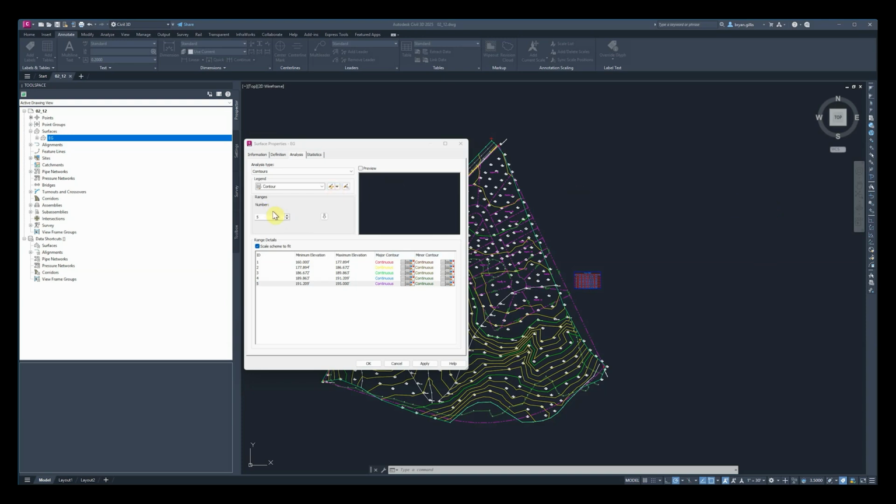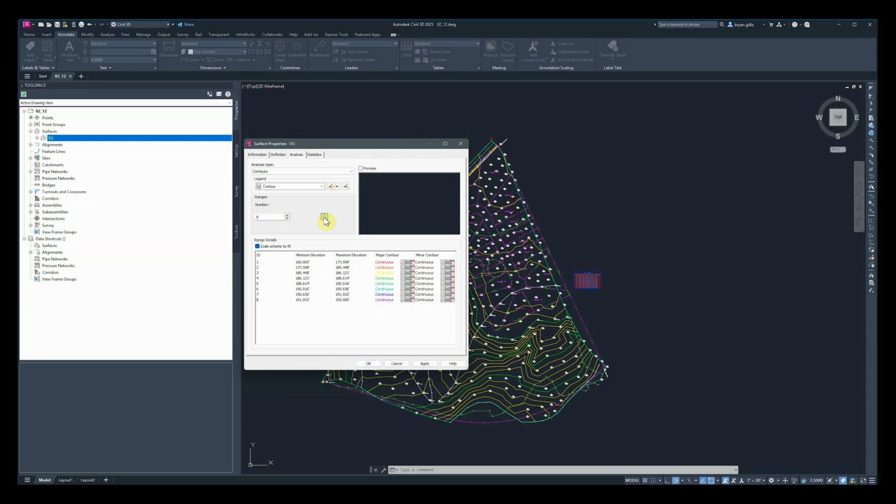So imagine we have these 5 here, but maybe we want to increase our equal interval classifications to 8. So go ahead and change that number to 8, click that Run Analysis tool, and then we now see our new sets of 8. One of the first things you're going to notice is some of these colors are pretty similar to each other. You know, this red and orange are going to bleed into each other, these 2 greens, and we're at 8 ranges.